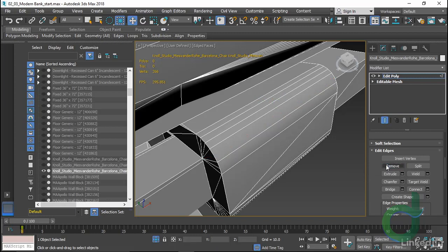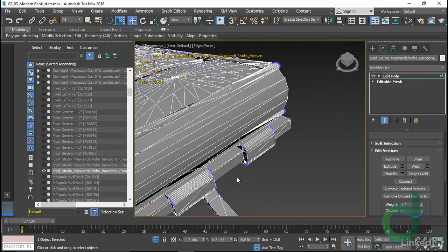If we hit Remove and then we press 1 for vertices, we see a vertex floating free in the middle of that edge. What I'll do, again, back to edges here, by hitting 2, is Clean Remove. Hold Control and click Remove, and now we see that the vertex is gone as well. This may feel a little bit cumbersome, but it's worth it to start reducing down some polys, as we have thousands in here. I'll work through the rest of this piece, and then if needed,